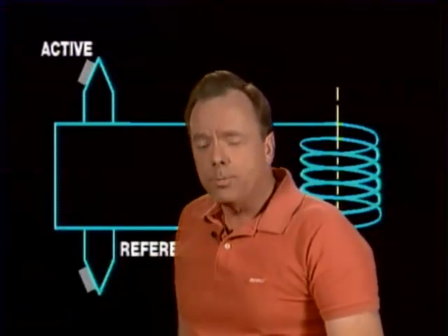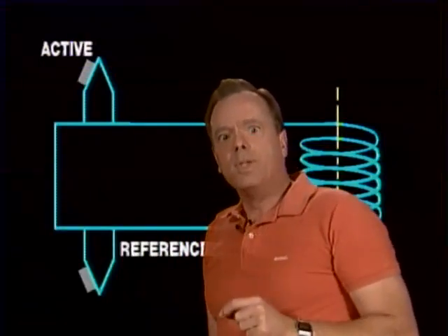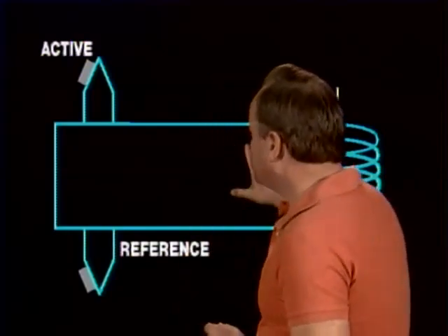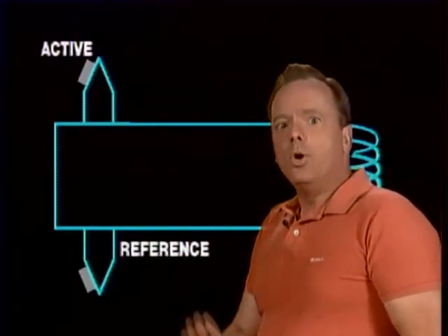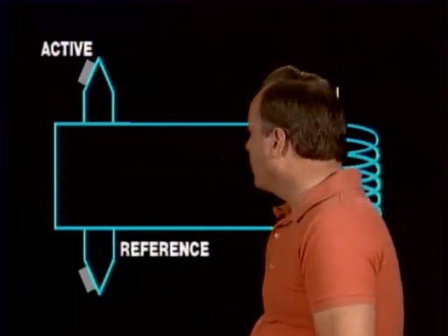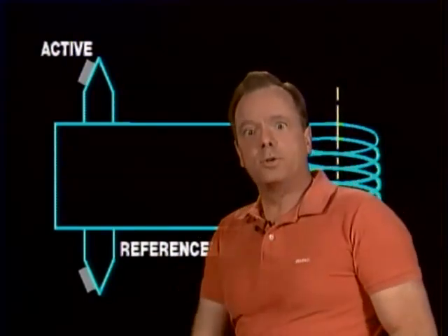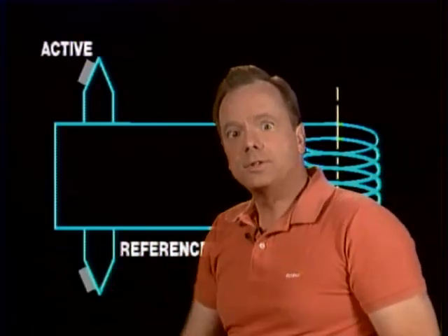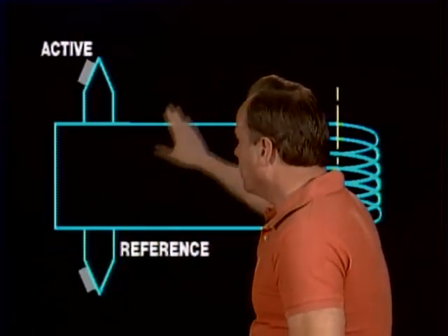All right, now let's talk about temperature indicating systems again. And we mentioned earlier a thermocouple type system. The advantage of a thermocouple type system is that it requires no power source. Thermocouples, by the way, are used for no electrical power source. So if the electrical system fails in this airplane, you still have this gauge working properly.